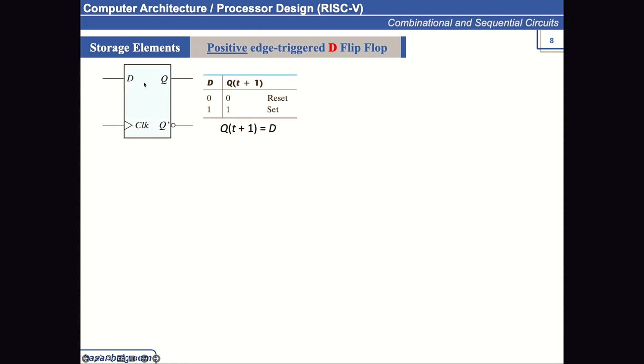The D flip-flop is usually represented with this kind of symbol. It again has digital circuitry inside it. D corresponds to data. So again, please concentrate on this. Whatever input we apply at D will be present at the output, which is labeled Q. But it will be present at the output only at the next positive edge of the clock. I'll explain in detail with the help of a waveform.